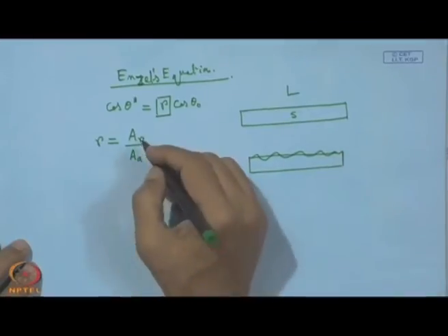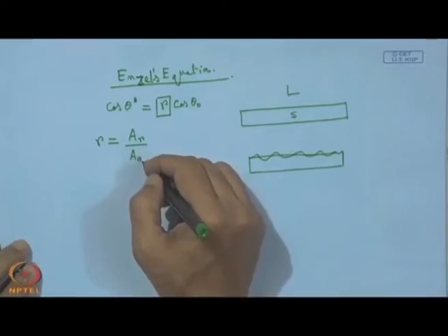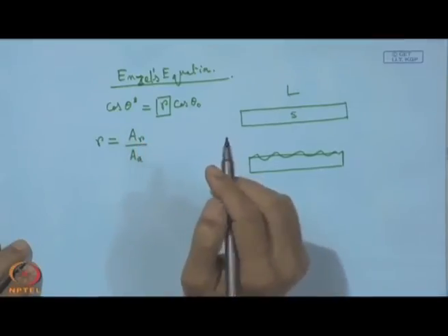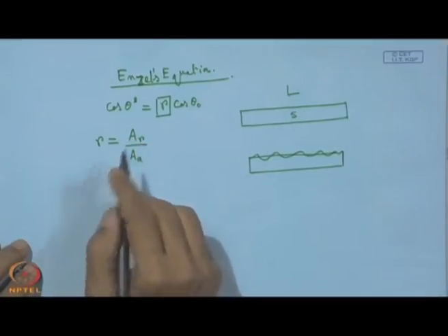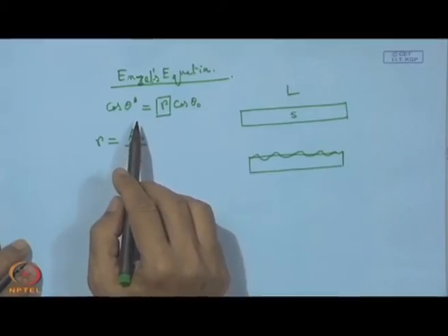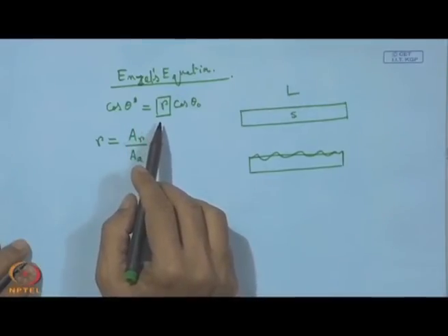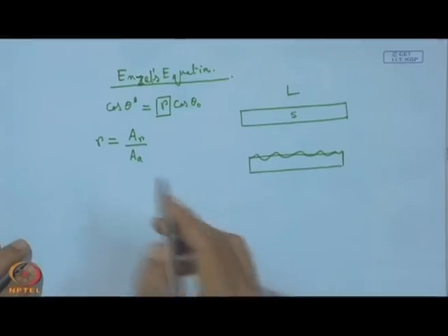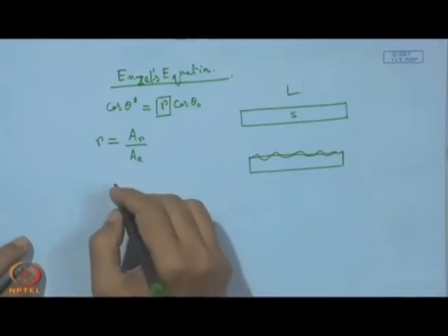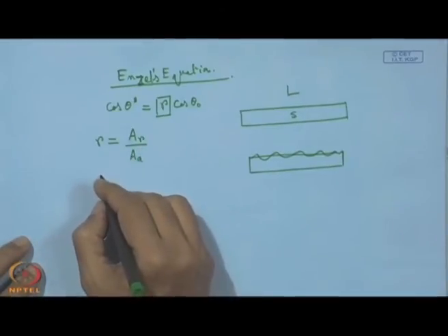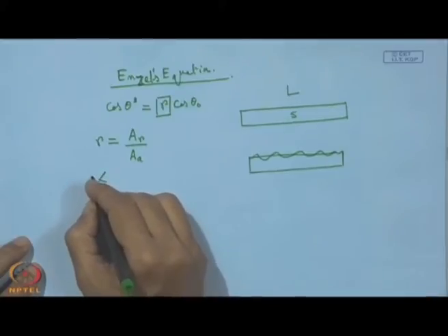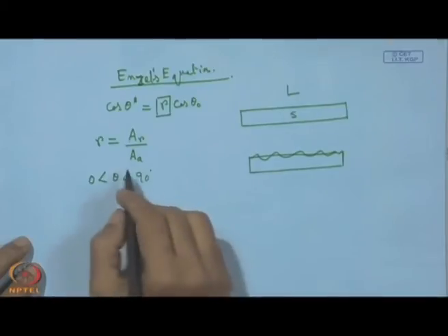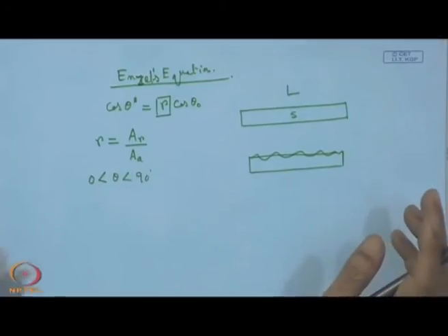Naturally the real area of contact with the liquid will increase, and obviously this ratio will increase. So, if it is an advancing liquid, that means there is normal spreading or normal wetting, in a situation where theta is in this zone, that means less than 90 degrees, that means it is a favorable case of wetting.